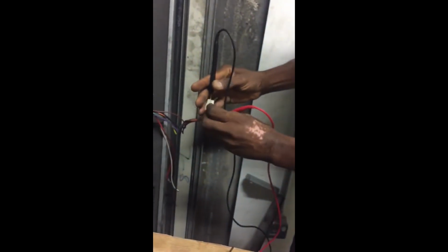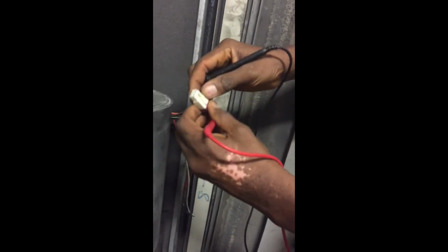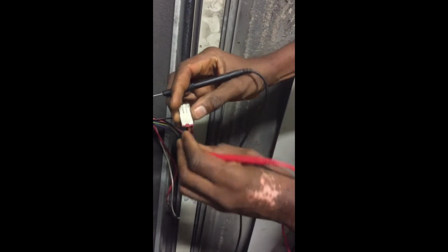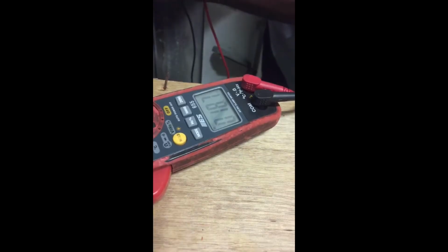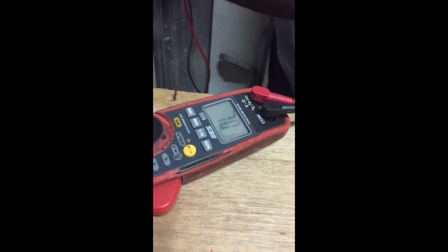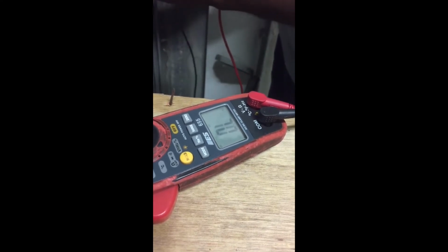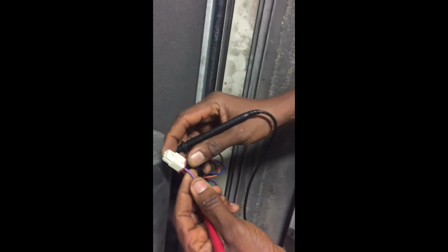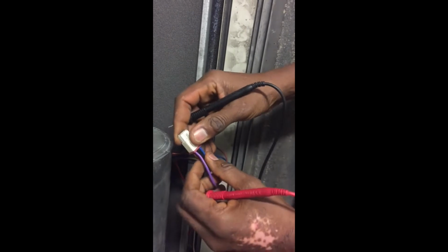Then let's try, which other color is there. Well, let's try blue and orange. So this is orange. Orange is here, which is the second terminal. This is orange, the other leg on blue. This is 18.7. This is obviously the highest resistance. So clearly the orange is the low speed, while the 15.6 is the medium speed, that is purple, and then black is the highest speed.